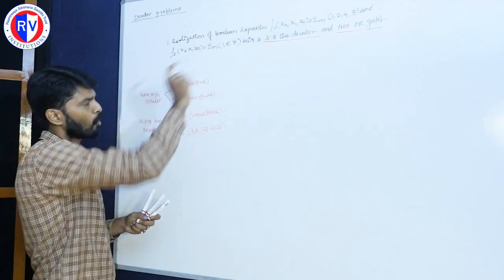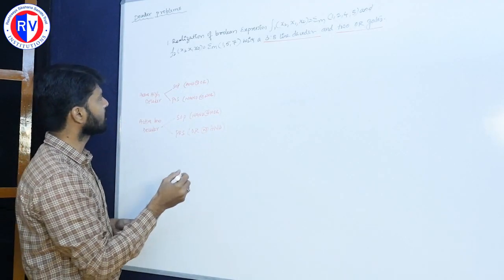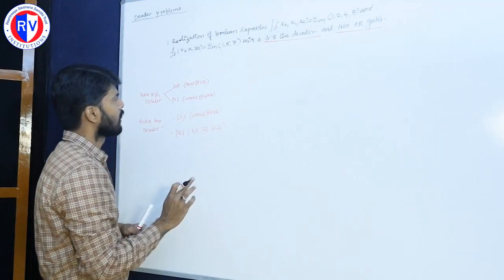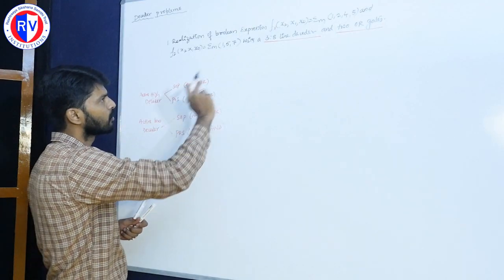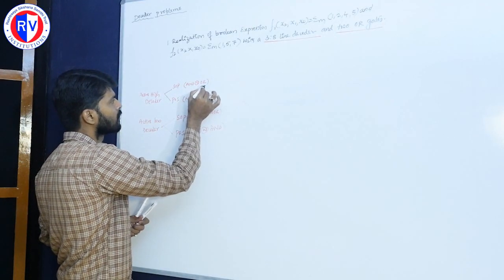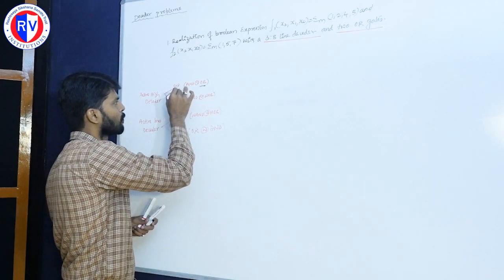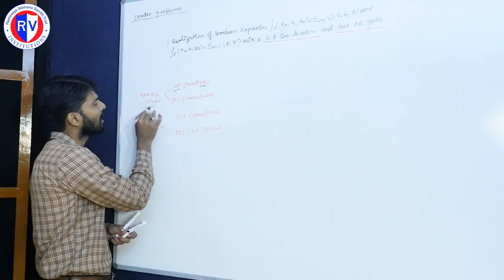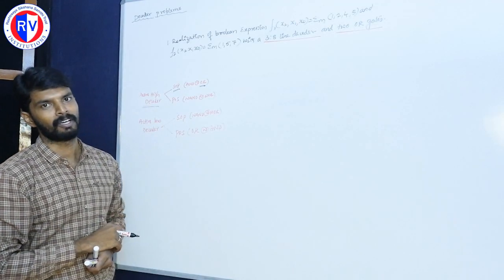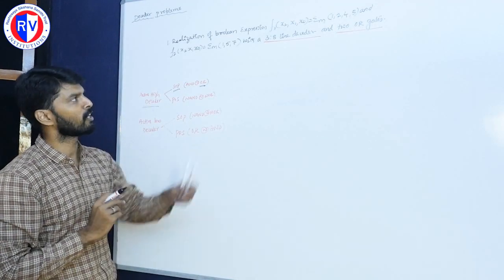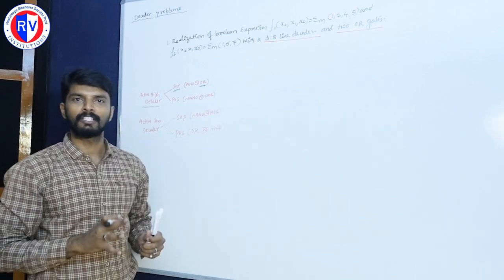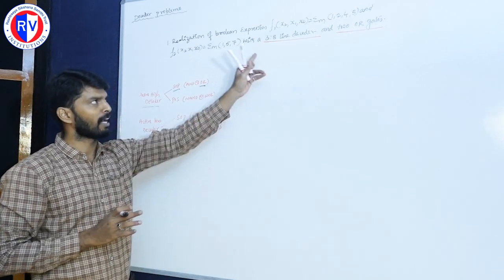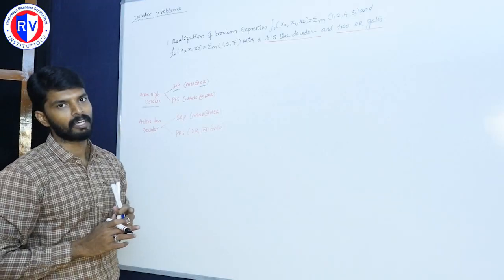But according to the problem, this is the SOP equation, and they told that I need to design using the OR gate only. This is the OR gate, and obviously this is the SOP equation. Then it holds good that we need to select an active high decoder rather than the active low decoder. Are you clear how to choose the decoder? In this problem they haven't mentioned which decoder we need to select, but the right choice is the active high decoder, correct? Are you getting?